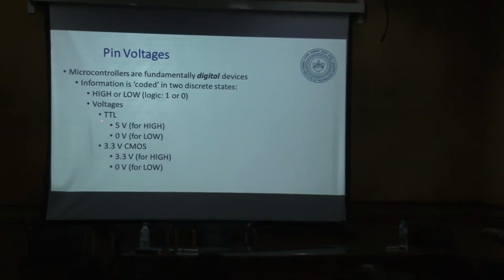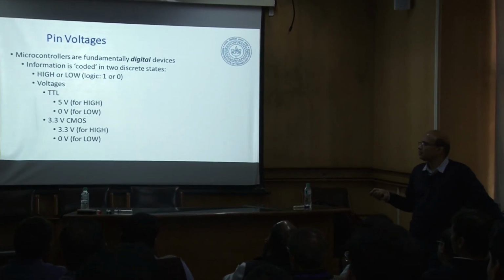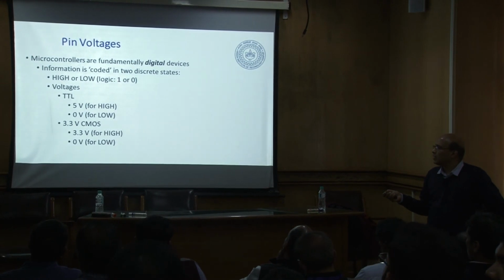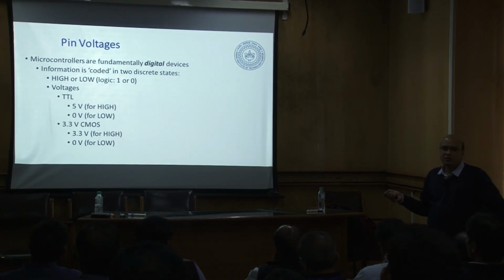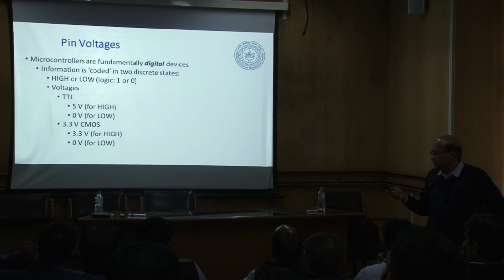And this is using TTL logic, which is transistor logic. Let's not worry about all that, it will be covered later. So a high essentially means 1, and a low means 0. I start off by saying my pin is an output pin or an input pin. Then I set that pin to high or low. If I want to give a voltage out, 5 volts, I simply say that pin number and high is 1. So 5 volts will go from that channel number out to whatever device is on that side. So high and low are defined by 1 or 0 in terms of logic.